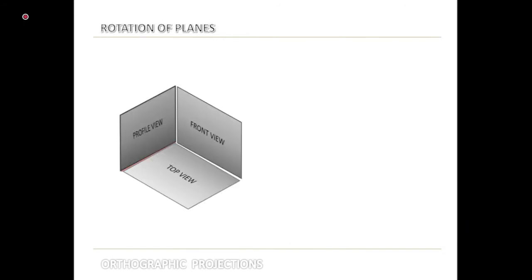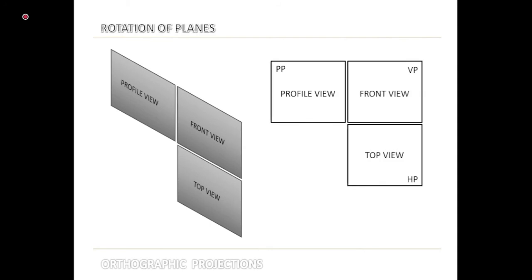You see the left profile plane, it is there on the left side of the front view. Which view are you going to draw on it, if it is a first angle projection? Right side view. Yes, always remember. If you are going to draw the right side view of the object, then you are going to draw it on the left side of the front view. Is this clear?